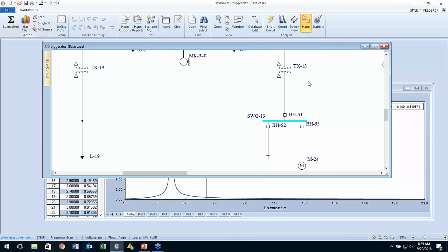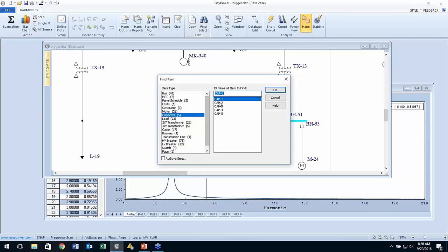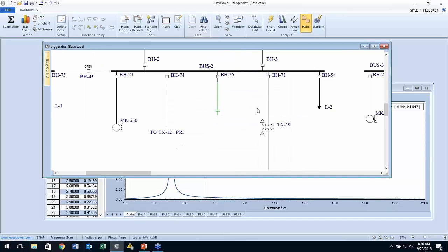And at that point, when you're down the road and you're just seeing a bunch of system issues, you are better off suggesting a harmonic study be done, and by using, at a first pass, just as I'm doing here, looking at in this case the high value capacitors, those would be the places we'd start off looking at, taking data log measurements for harmonic content and power quality measurements.